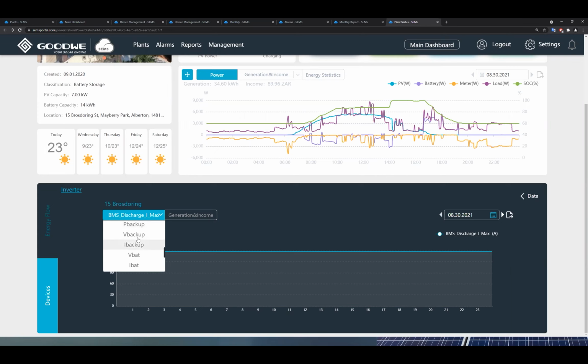And then the P meter section is used to confirm that our meter is installed correctly, especially on the 3-phase, where you can view the individual meter data, and that gives us a good indication of whether the meter is installed correctly or the CTs are correct. Because sometimes with the 3-phase, it might look correct on this main graph, but because all of the load is on one phase and the other 2 phases have very little load, that doesn't make it look incorrect.